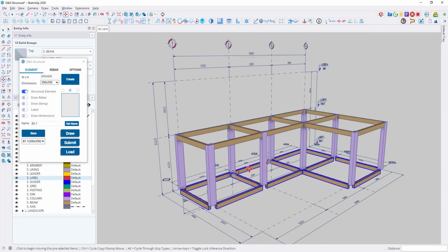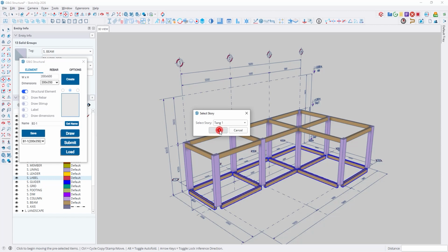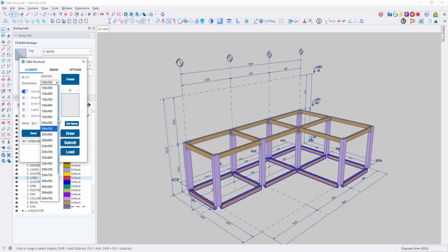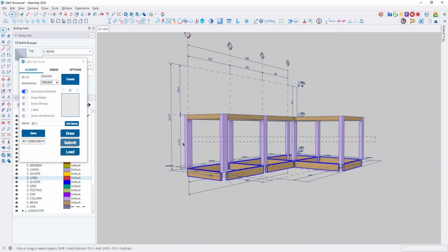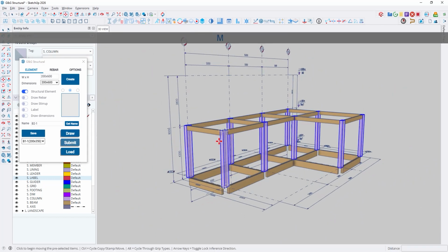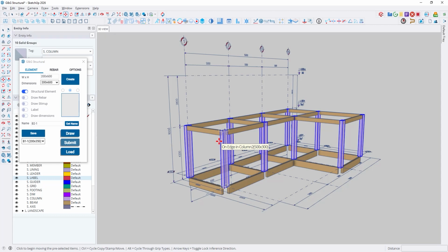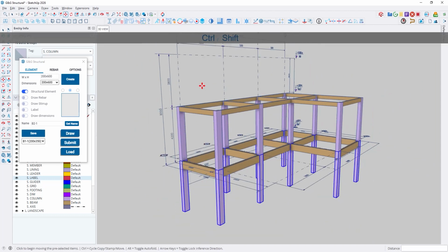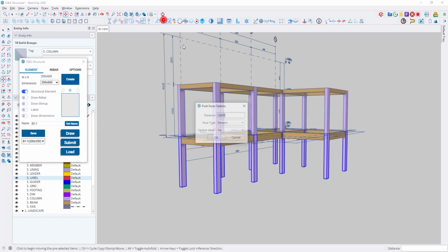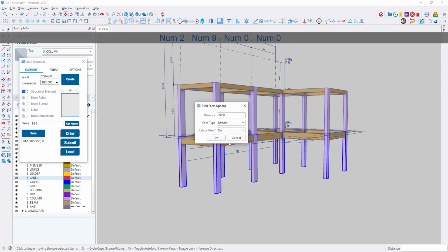Additionally, we can copy components to create new objects. At the same time, you can change the cross-section for multiple objects in a single action. Batch editing saves a lot of time during model deployment. Similar to columns, the plugin also supports batch copying and editing of heights, lengths, or other geometric parameters through the Quick Edit module. This is especially effective when you need to update structural options during the design process.